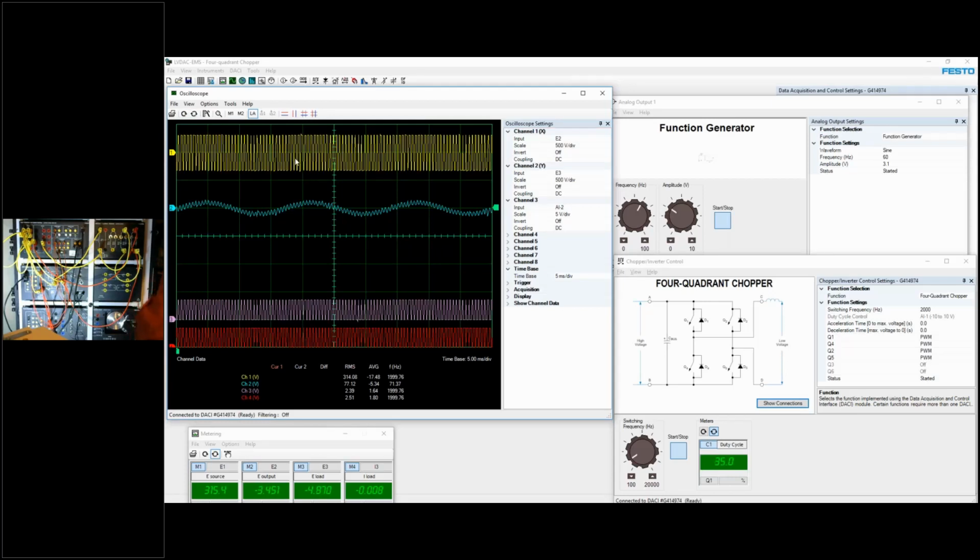You can see that when we are at the positive peak of our sine wave, if we look at the corresponding signal, well, in fact, it's not the triggering signal. This is the output of my H bridge, sorry. But you can see that to this peak corresponds the location where all the pulses are wider at the top, so in the positive half of the cycle, while the negative portion of my sine wave corresponds to where the pulses are wider at the bottom, so in the negative half of the cycle. So this is how there is a direct relationship between this and this.